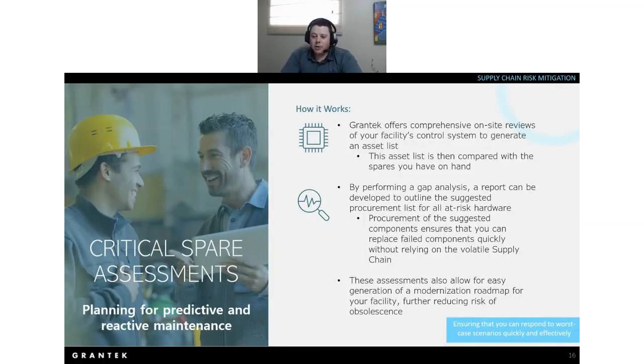Now there are a few options, and maybe I'll talk specifically about this request for an HMI, and this one I believe was a PanelView. Oddly enough, we've seen this more often lately because PanelView lead times are very long right now. So one thing that we've done is suggest alternative or in-kind replacements. For a PanelView specifically, one thing we have designed is replacing the PanelView in total with an industrial PC and an associated touchscreen, panel-mounted monitor. What that allows you to do is install software and license the IPC accordingly to basically mimic the PanelView. So the same application can be downloaded to it, but the lead times on IPCs and touchscreen monitors are far less than that of a PanelView.